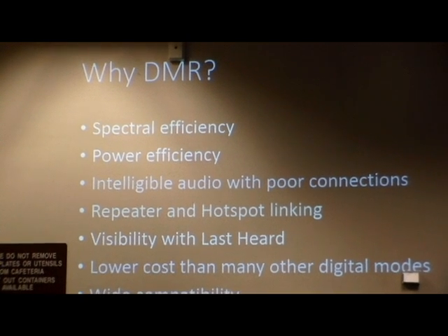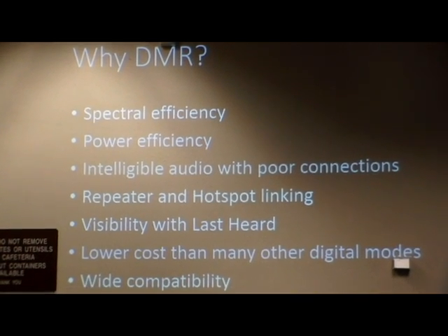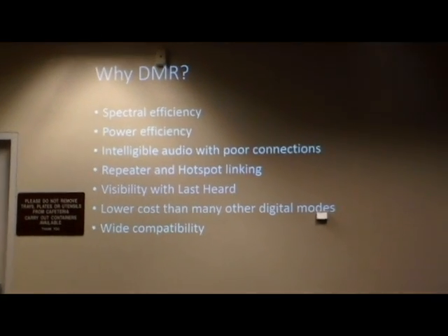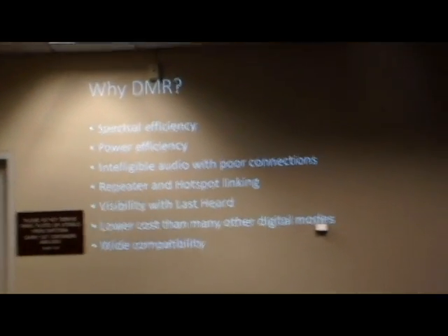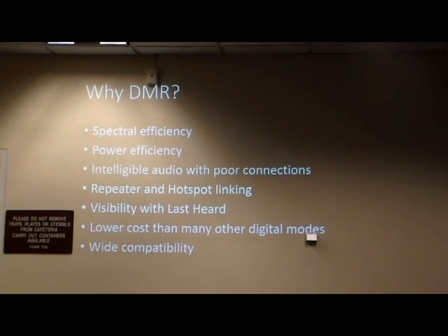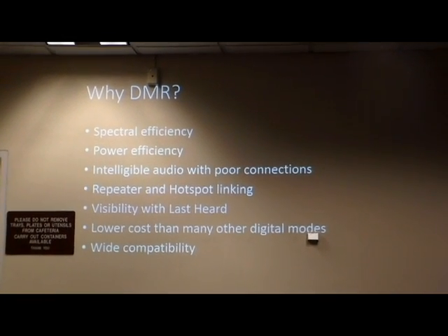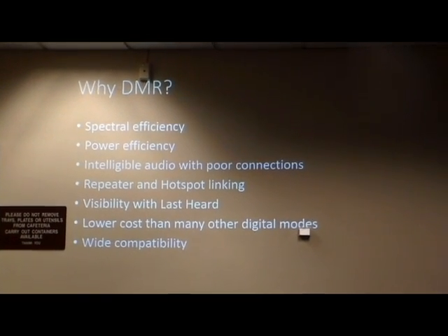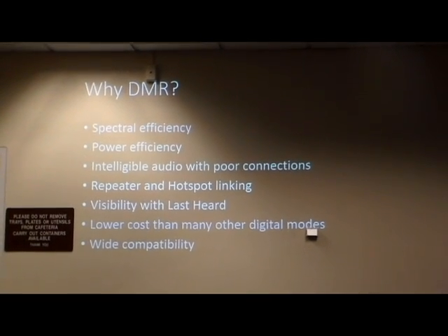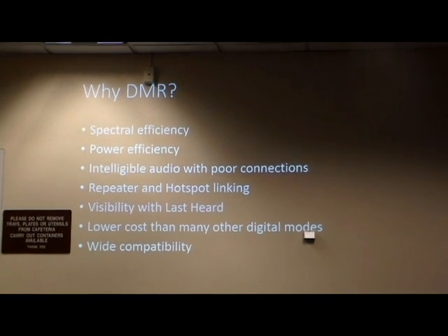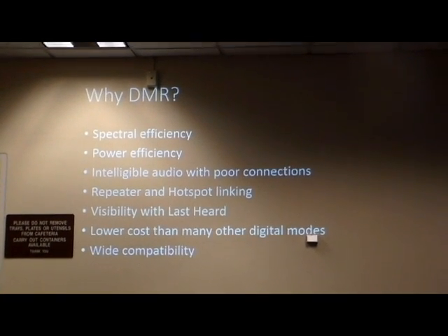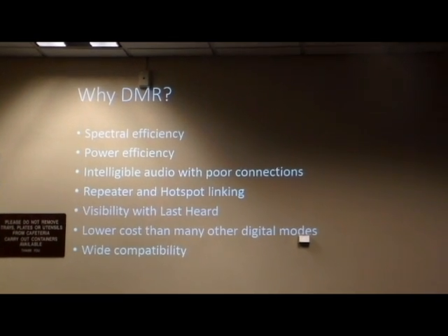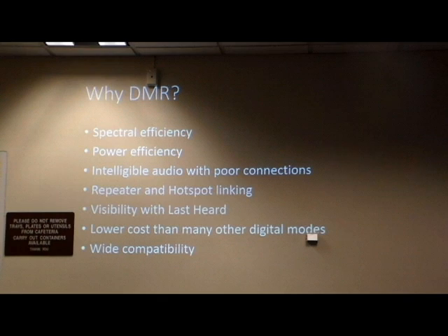So I realize I'm probably way over time here. Sorry, but I just want to go over why be interested in DMR at all, right? Just a couple of the benefits. Spectral efficiency, being able to have two conversations in the same 12.5 kilohertz channel using time slots. Power efficiency, potentially up to 40% better battery life. Intelligible audio with really poor connections. Times when FM would be scratchy and you wouldn't be able to understand someone, forward error correction can help you get an understandable signal through.